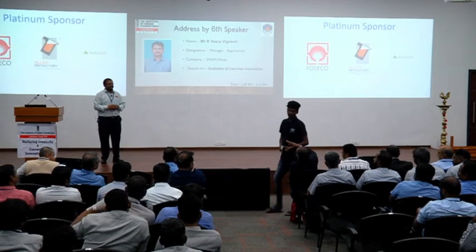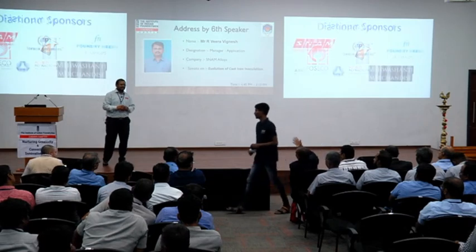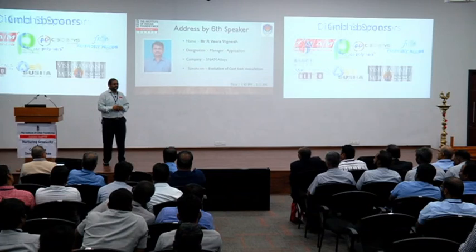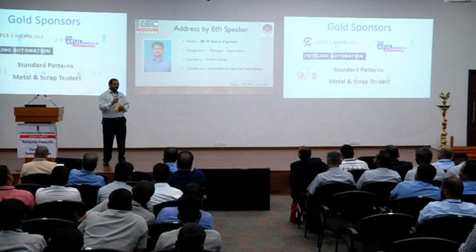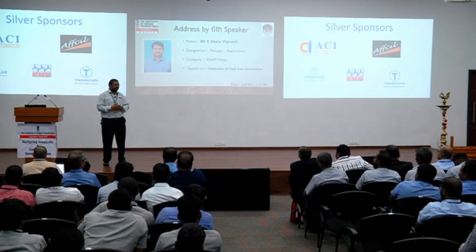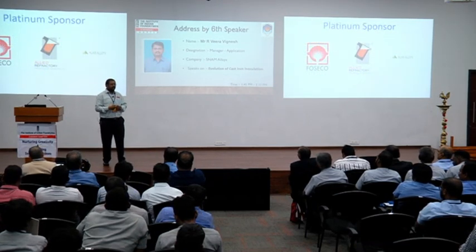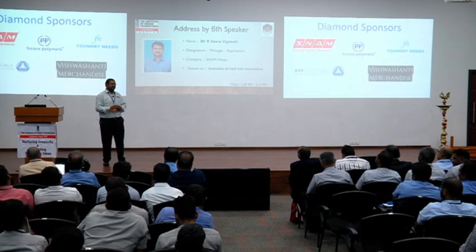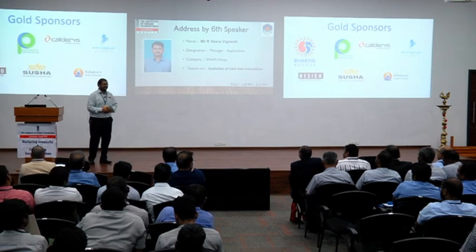What is the qualification method for the inoculant or the measurement of the nucleation potential? Say, will the charge variation be there? Sir, no change in your defect or rejection percentage with respect to the same property which you are measuring, no change in or reduction in your rejection percentage related to metallurgical factors, not pouring defects, sir. Say if your carbide percentage comes down, your steadite percentage comes down, or your type D percentage comes down, or your uniformity nodule count increases, then those are the measures of inoculation. After the production. Yes, sir.